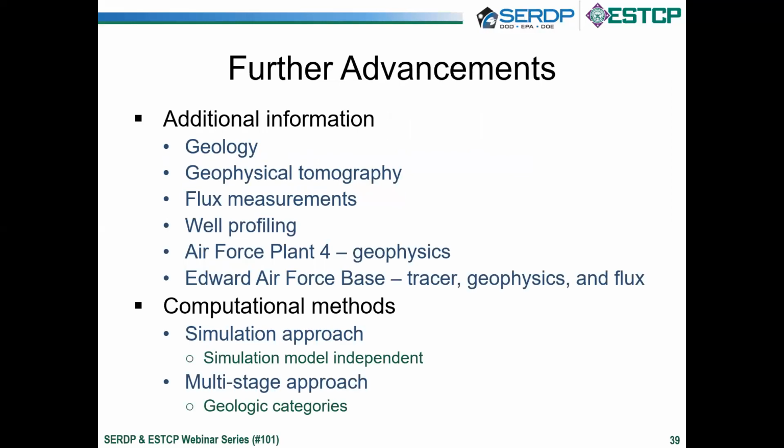To end, I'm going to talk about a couple of further developments that we are doing with the hydraulic tomography technology. We are also trying out at 2 other Air Force sites demonstration with the incorporation of geophysical information, electrical resistivity survey, to enhance the result of hydraulic tomography. One is at the Air Force Plant 4. We perform ERT to improve the result of hydraulic tomography. And at the Air Force Base, right now, we are doing tracer enhanced geophysics to look at the migration pathway.